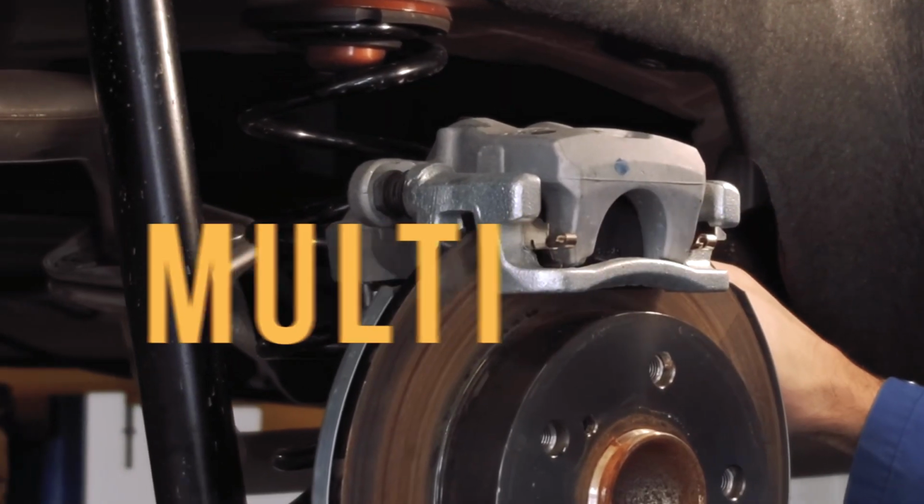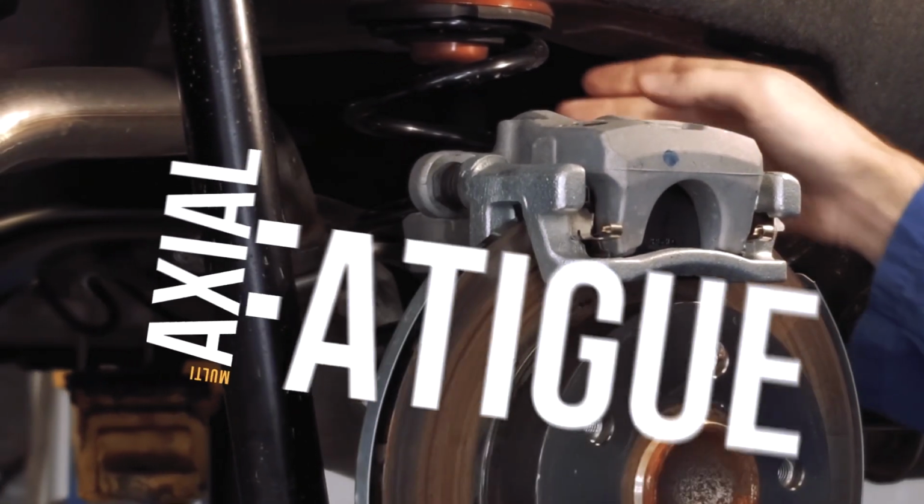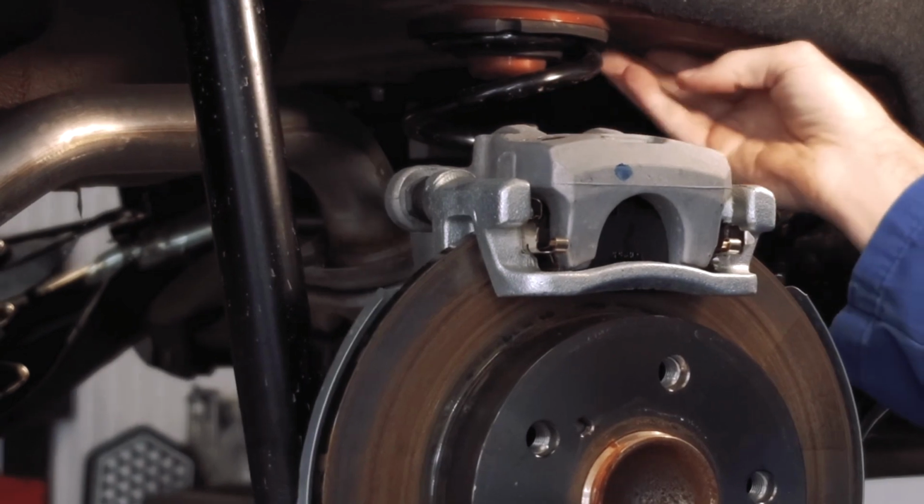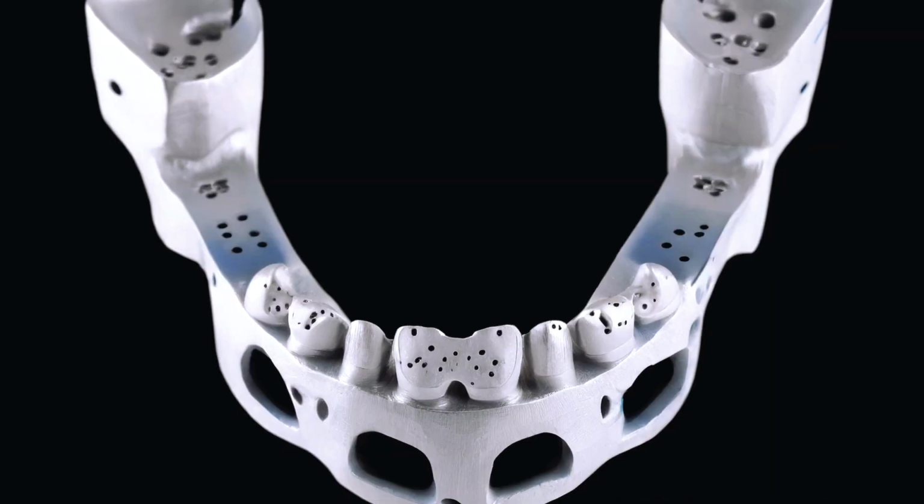Suspensions are optimized using multi-axial fatigue criteria like the Findley criterion to account for combined bending and torsional stresses. For orthopedic implants, surface treatments like diffusion hardening optimize the balance between fatigue strength and wear resistance. Implants are tested in simulated body environments, accounting for effects of moisture and temperature on fatigue life. While we covered a lot in this video, there's still so much to explore about this complex topic.